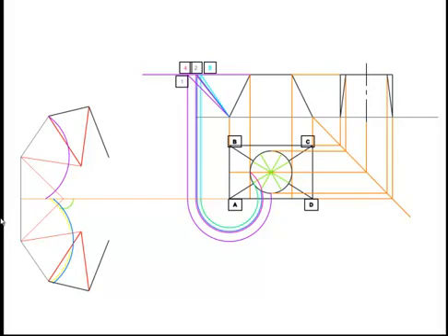Now we do the same thing again. We get the yellow line and swing another point, which will create another point in the development, and likewise again with the purple line. This will create 3 points in plan on the development, and again another point, which will be our 4 points, which will be 1, 2, 3 and 4 in plan and brought over to the development over here.